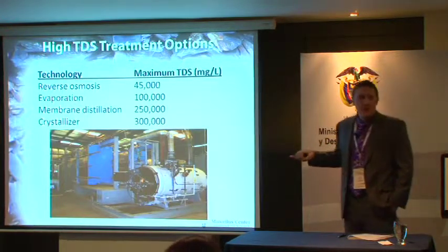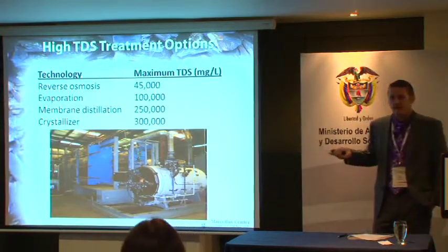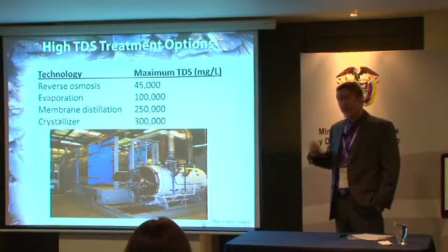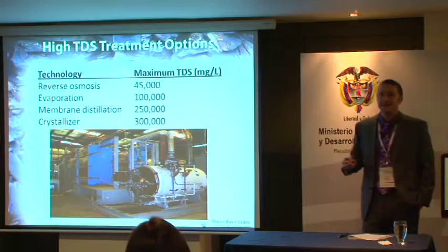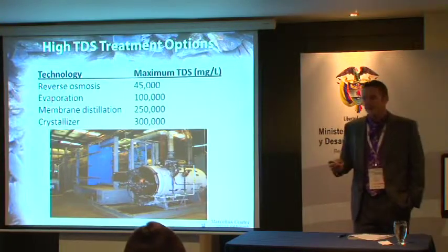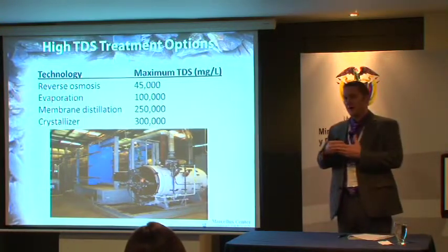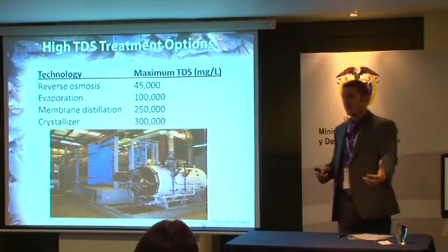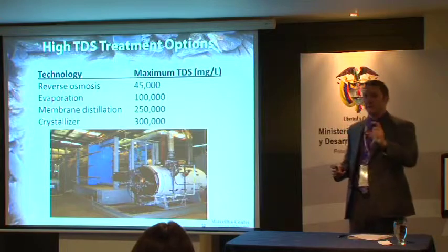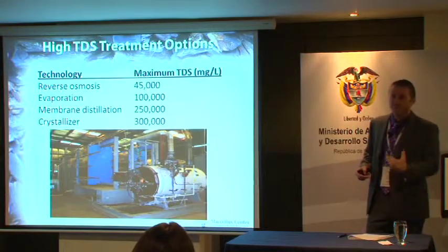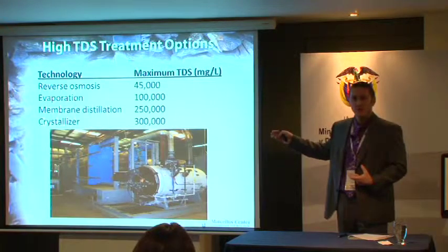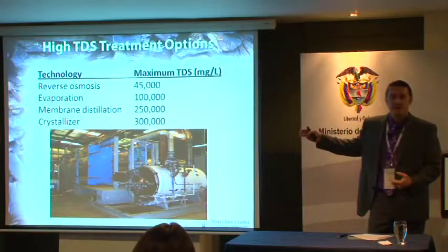The salt in the water represents a challenge to remove, because it's an energy-intensive process to desalinate water. So that's why many of the operators will choose to remove the scaling agents, those metals, but leave the salts in. And again, if you recall, I'd mentioned the fact that we have brine-tolerant friction reducers. That's really sort of the key to allow the recycling of this water without desalination.